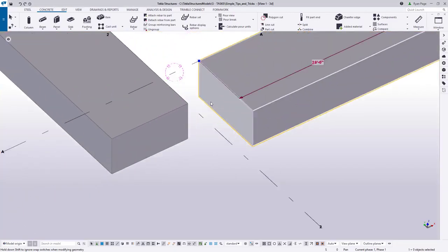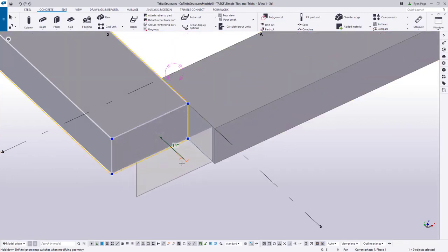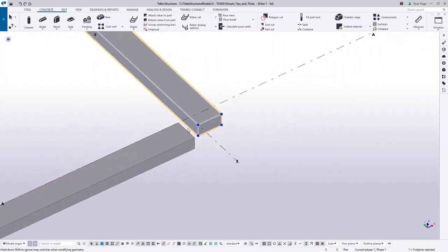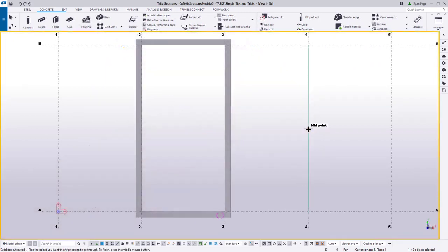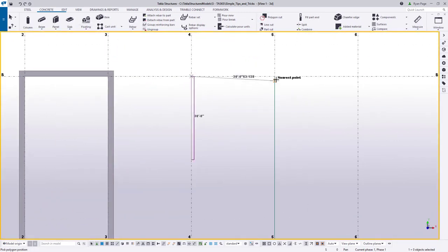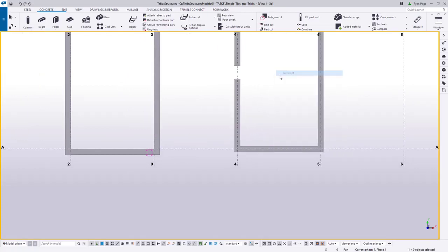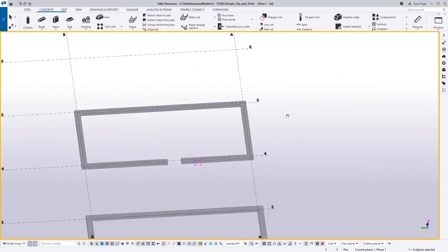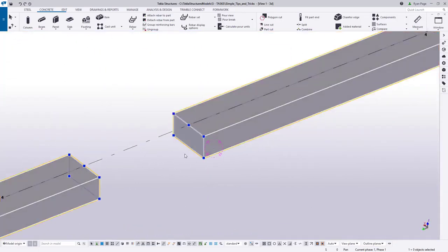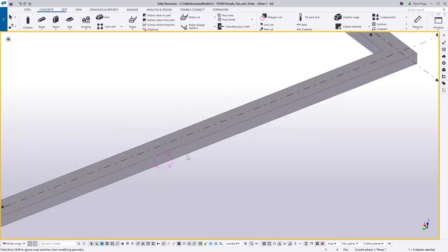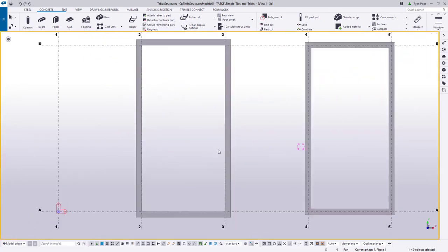You can actually model a closed footing or polybeam for that matter, as they're essentially the same tool. All you have to do is change how you start your footing or beam. The trick is to establish your starting point not at one of the corners, but along the length of one of the sides. Doing so allows you to complete the continuous shape just short of the starting point, and use direct modification to close the gap, leaving you with a closed continuous footing or polybeam.